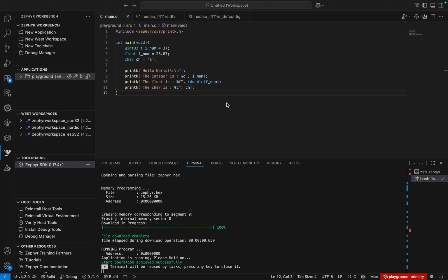And this is why in Zephyr and in many other embedded systems frameworks, they leverage one of the serial communication techniques, and it's usually the UART that is chosen for logging information. So basically, there's going to be a UART connection between your microcontroller or your hardware and your host computer, which is a computer on which you are writing your code, compiling and uploading onto the MCU.